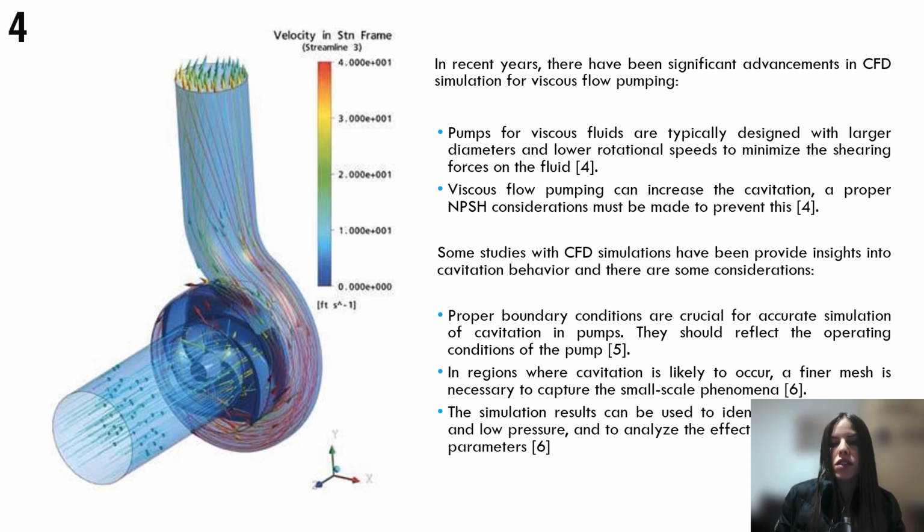Some studies with CFD have been providing insights into cavitation behavior, and there are some considerations. Proper boundary conditions are crucial for accurate simulation of cavitation in pumps. In regions where cavitation is likely to occur, a finer mesh is necessary to capture the small-scale phenomena.